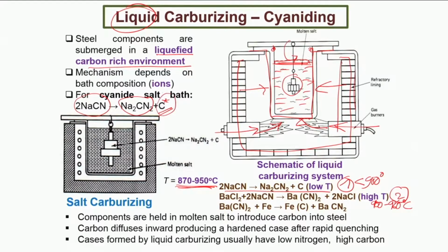So this nascent carbon, like in the previous case, if this is the workpiece that we are talking about, then this is the workpiece which actually is covered with this nascent carbon, which gets adsorbed to the surface. So this is initially just a chemisorption process, and then subsequently, because of the high temperature environment we are maintaining, which is an isothermal temperature, carbon diffuses inside the material up to a certain depth.